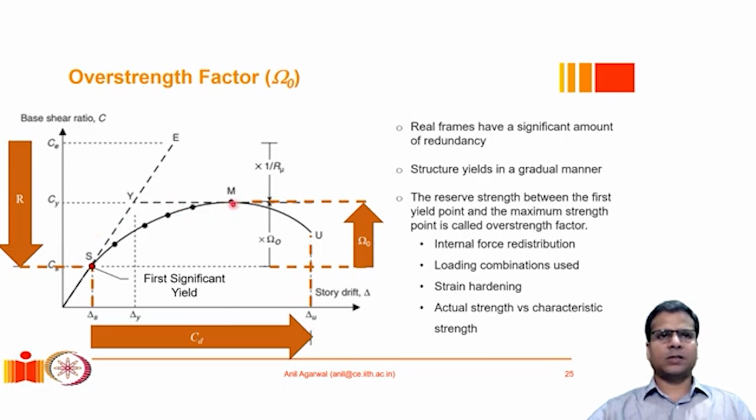So the DCE system, which is transferring the same force to the FCE, this is the response of the DCE system. And the FCE system, which is an elastic system, that is transferring the force to the DCE component, should not plasticize anywhere from here to here. So we do the basic elastic analysis to get the demands up to this point.